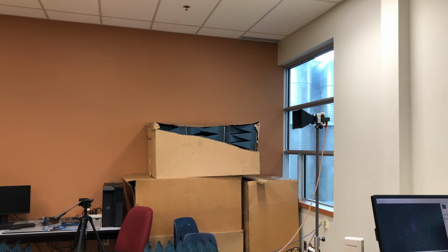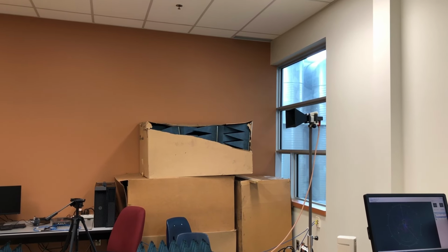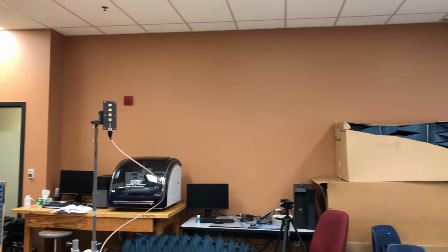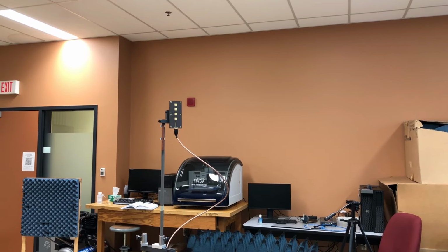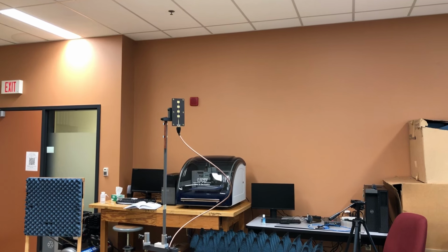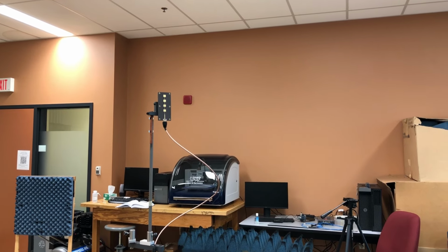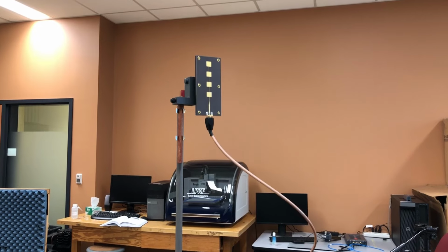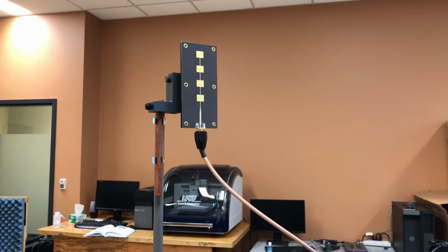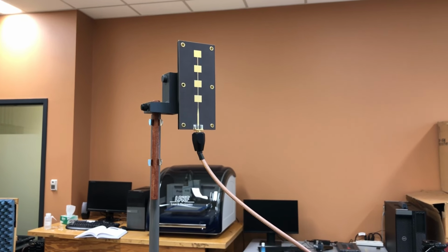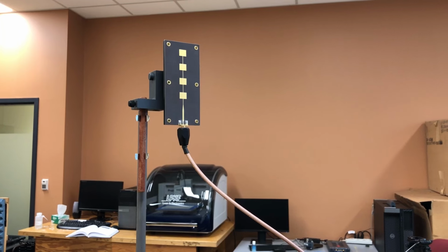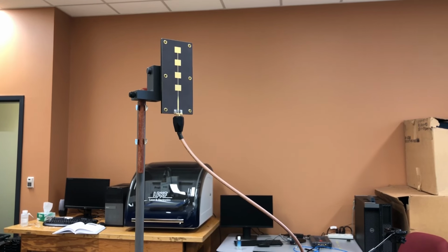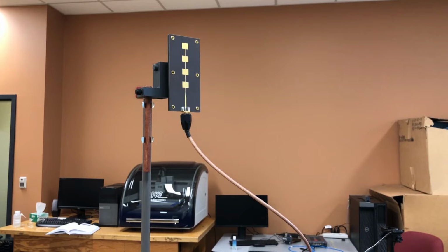Okay, in this video right now, you see that we have our horn antenna vertically polarized. That's our transmit antenna. And now we're going to go to our antenna under test, which is the series fed patch, which also expects a vertical polarization. It has been mounted right now. I'll get closer to the antenna so that you can see that more clearly. That's our series fed antenna. Now I'm gonna start data collection, and with this type of rotation, we're gonna get H plane because the polarization is also matched. That's gonna be our copole H plane.